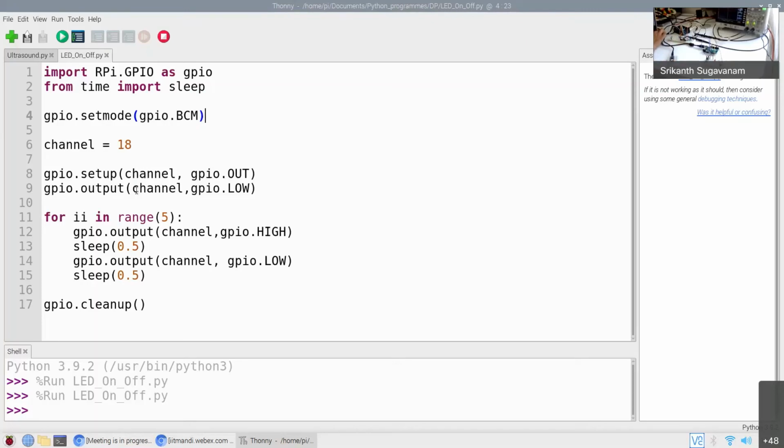Okay, so it sends out a series of ultrasound pulses. One end sends out a series of ultrasound pulses. It reflects off an object, and then it comes back to the receiver, which is the other head. Internally, you have electronics which measure how long the pulse has been traveling in air. Once you know that, because you know the time of flight, you can calculate the distance to the object. All right. So this is how an ultrasound distance sensor works at a very basic level.